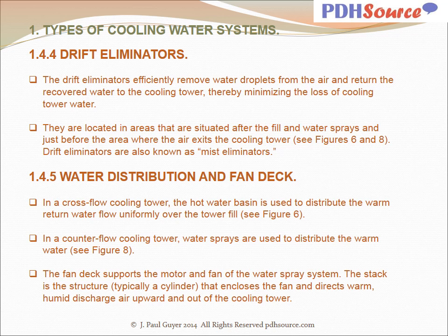In a cross-flow cooling tower, the hot water basin is used to distribute the warm return water flow uniformly over the tower fill. See Figure 6. In a counterflow cooling tower, water sprays are used to distribute the warm water. See Figure 8. The fan deck supports the motor and fan of the water spray system. The stack is the structure, typically a cylinder, that encloses the fan and directs warm, humid discharge air upward and out of the cooling tower.